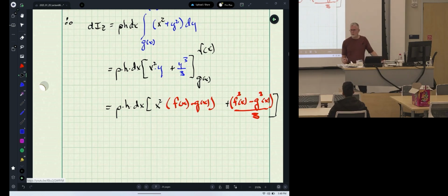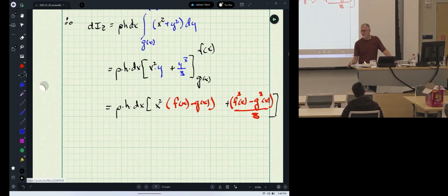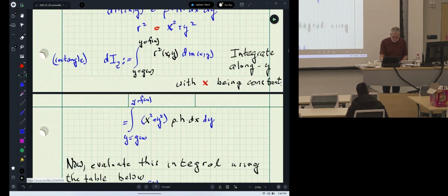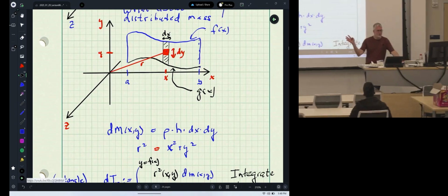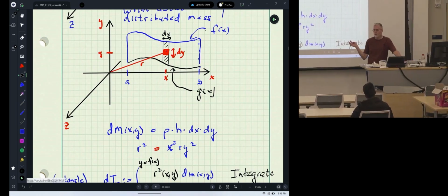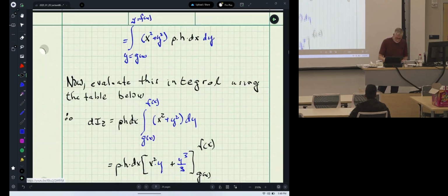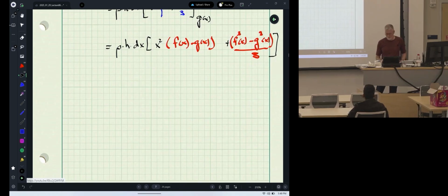How many of you got that or something really close? Wow! Is that the most awesome formula you've ever derived in your entire undergraduate career? Close, isn't it? If not, it's very close. So now, how do we get the total contribution? We know the moment of inertia of this rectangle. How do we get the total moment of inertia of this body about the z-axis? We just add up the contribution of each of the rectangles, and that's it. And we get a doubly awesome formula, okay?